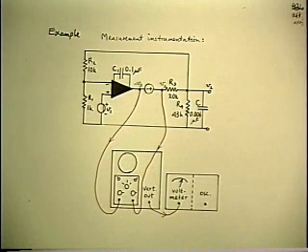So what you do actually is measure the 3 sides of a phasor triangle. And then you dig back into your memories of old high school trigonometry, and you remember there is a formula that says if you know the three sides of a triangle, you can calculate the angles, known as the cosine formula. Maybe you've forgotten it.